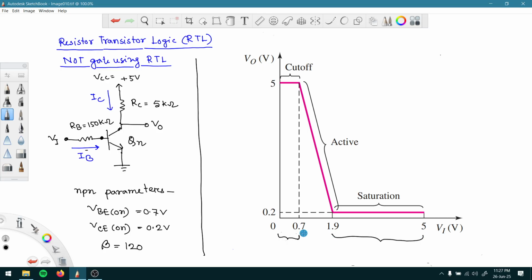And we know that the maximum possible voltage that the logic gate can interpret as logic low is actually VIL. So this is the maximum value allowed for the input, so that it can recognize it.